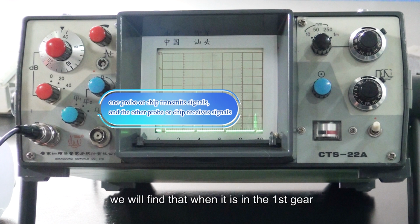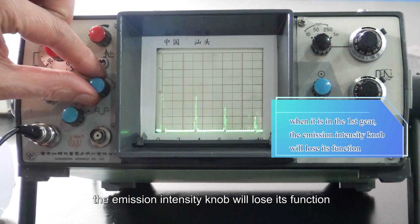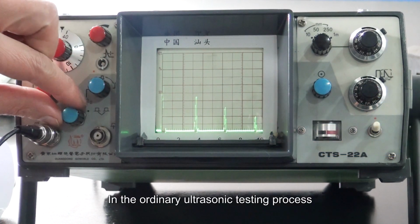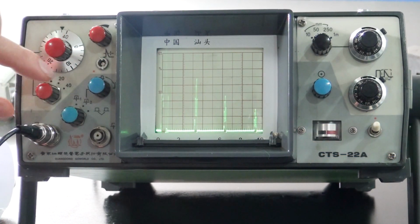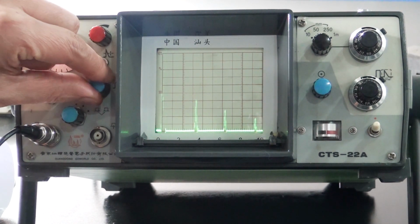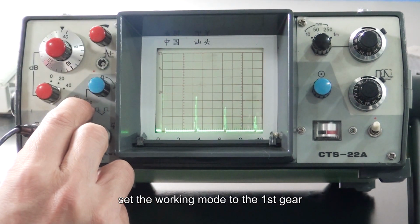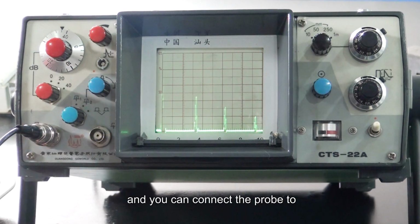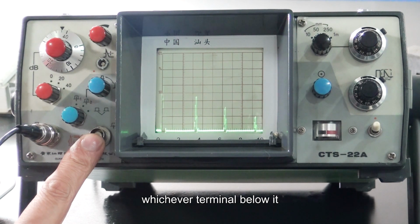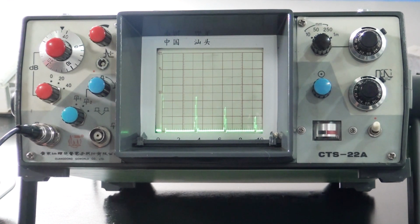Let's demonstrate. We'll find that when it is in the 1st gear, the emission intensity knob will lose its function. In the ordinary ultrasonic test process, most of the time, it is a single probe test, so usually you only need to set the working mode to the 1st gear, and you can connect the probe to whichever terminal below it, because the interior is connected at this time.